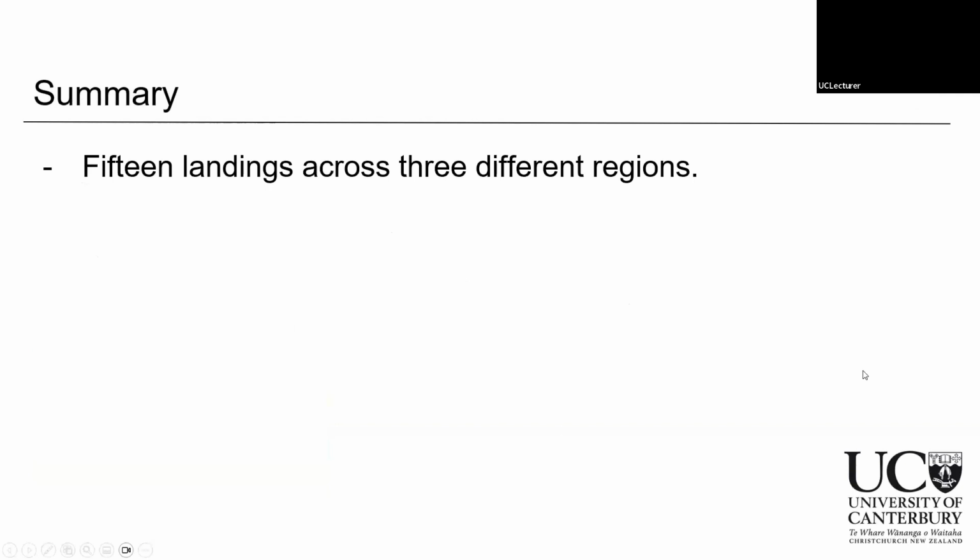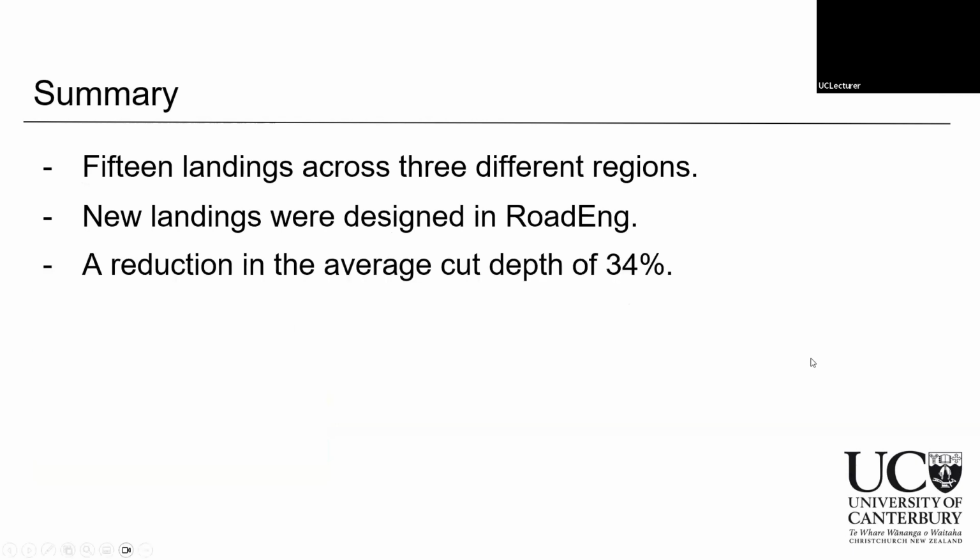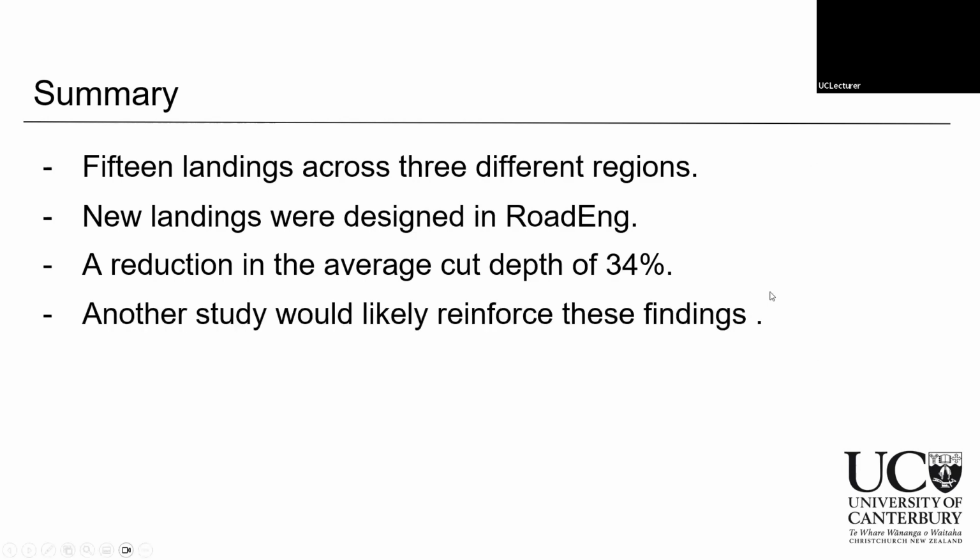So to summarize, digital elevation models of 15 landings across 3 different regions were taken from Land Information New Zealand, and new landings were redesigned in Road-Eng. It was found that these redesigned landings had a reduction in average cut depth of 34%. Showing that it was in fact possible to create a landing with an equivalent surface area for a small amount of earthworks.